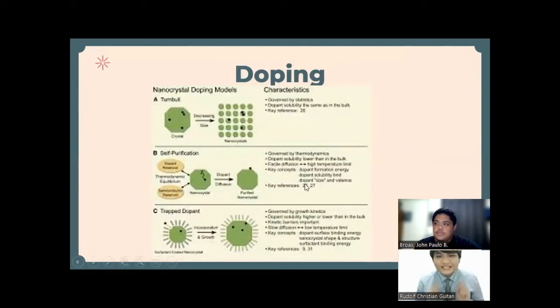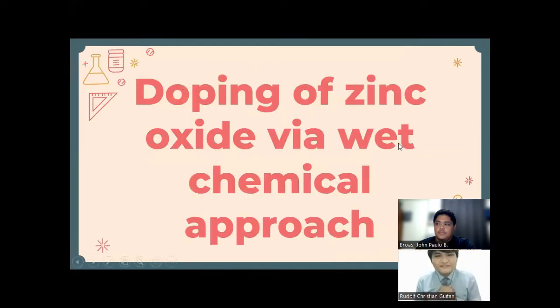Doping is the technique used to change the properties of materials by changing the number of electrons and holes. There are two known types of doping, p-type doping and n-type doping. P-type doping adds atoms that create vacancies or holes, which are the majority carriers, while n-type doping is where the majority carriers are the ones that add extra electrons, called donor atoms. One example of n-type doping is zinc oxide. This is because of its oxygen vacancies occurring in intervening spaces which are occupied by zinc ions.